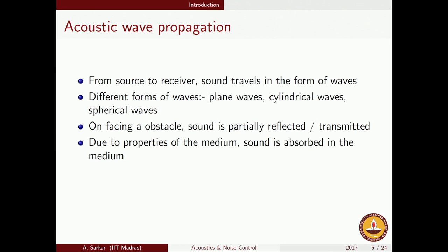So, one issue that is definitely there is that all mediums will have certain losses associated with the properties of the medium. Other than the process of sound transmission, there is also a process of sound absorption. Sound absorption happens due to two main features. One is the viscosity of the medium. As you know, fluid viscosities play an important role in the dynamics of the fluid, and the viscosities are usually treated as a sort of head loss in the case of mean flow effects.